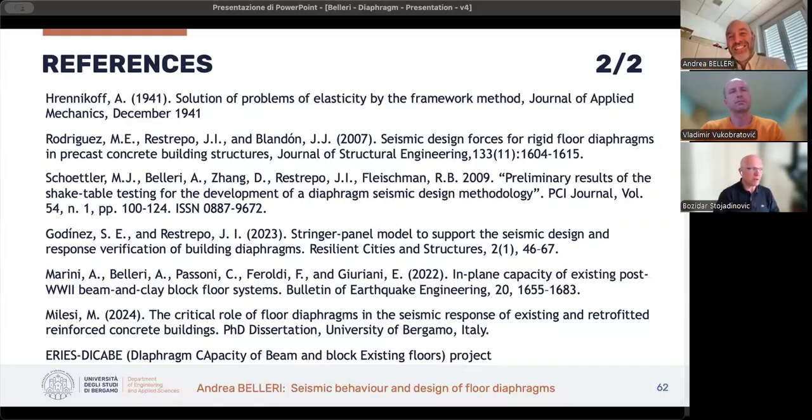No, I agree about the elongation. I think it's quite large when we test solitary beam column elements. The New Zealand estimates are not that wrong. However, if that was actually happening in the building, we would probably see a lot of this. My expectation is that a lot of that elongation is restrained by the floor slabs that are more competent than the ones that we have, and the interaction between the edge beams or the beams of the moment frame and the floor slabs is complex, to understate the situation.